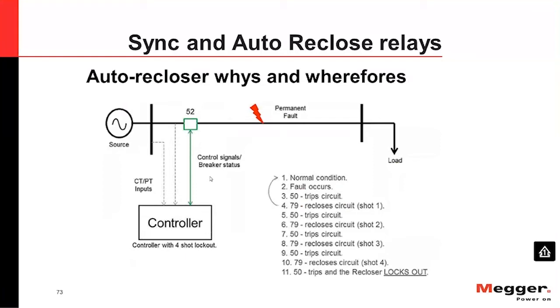Commonly, our standard says only instantaneous faults should do that, but overcurrent faults, which are time delayed, should not. That is because time delayed means there is really a fault over there, but for instantaneous, there is no real fault. Maybe it's because of a 3-phase down over there, maybe something transient like the bushing is not cleaned well, or maybe there is lightning, something like this.